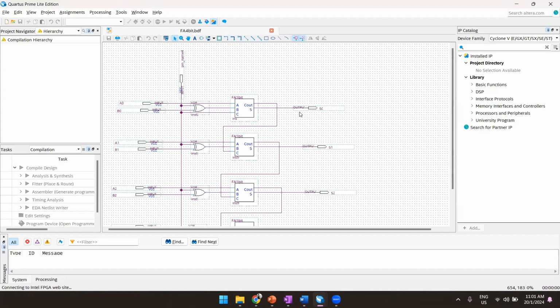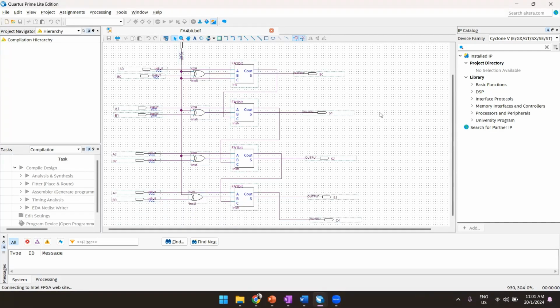Okay, now I'm going to talk about the block diagram of the adder and subtractor. After the values of A and B are obtained from the multiplexer, they will be used as the inputs for the adder and subtractor. So we use a ripple carry adder to build the adder and subtractor block diagram. As an example, when both numbers A and B are selected from the multiplexer, the input of B will be connected to the XOR gate with C0, where C0 is the initial carry and also the ALU OP.